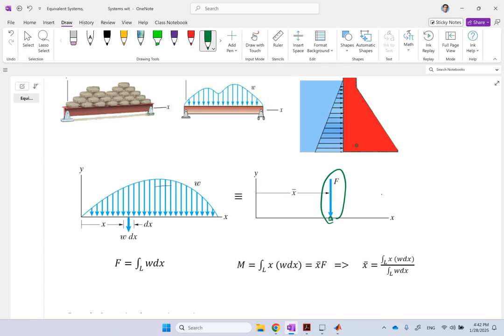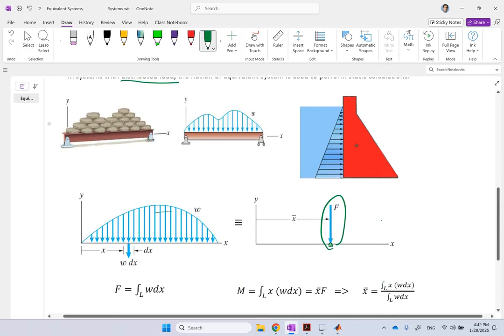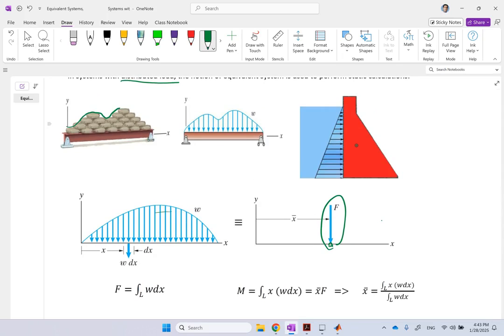Now, sometimes the surface over which the load is distributed is bigger. You can see it visually, right? So for instance, if you look at this beam and all of these sandbags that are on it, in some places there are more sandbags, some places less, then you can say roughly the weights of all this sand can be approximated by this kind of distributed load. And there is this load density omega or w(x), which is a function of location. So it's a curve, it's a function, right?